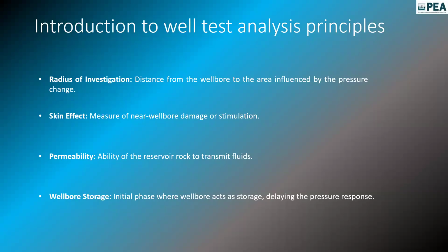But how much time does it take for this pressure disturbance to reach from the wellbore to the end of the drainage boundary? That time we name as transient time. The time taken for the pressure disturbance from the wellbore to the drainage boundary is the transient time. Imagine transient time might take around 8 hours after opening the well.